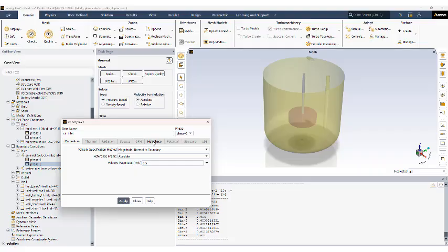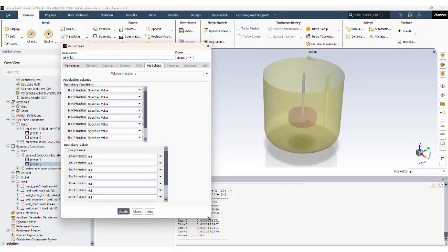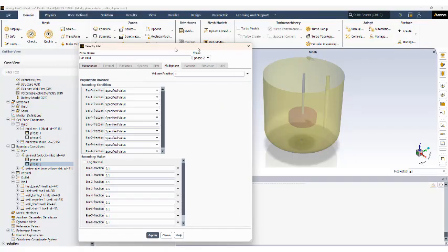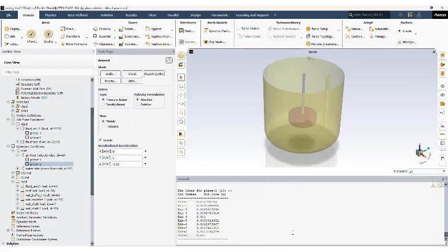And if you go into multiphase, you can define what kinds of bins or what kind of bubbles you're going to add in terms of the fraction of each. The volume fraction for the bubbles for the PB phase is 1. And I set everything to 10%. So basically we have a uniform injection of bubbles into the tank. And then I can close that.